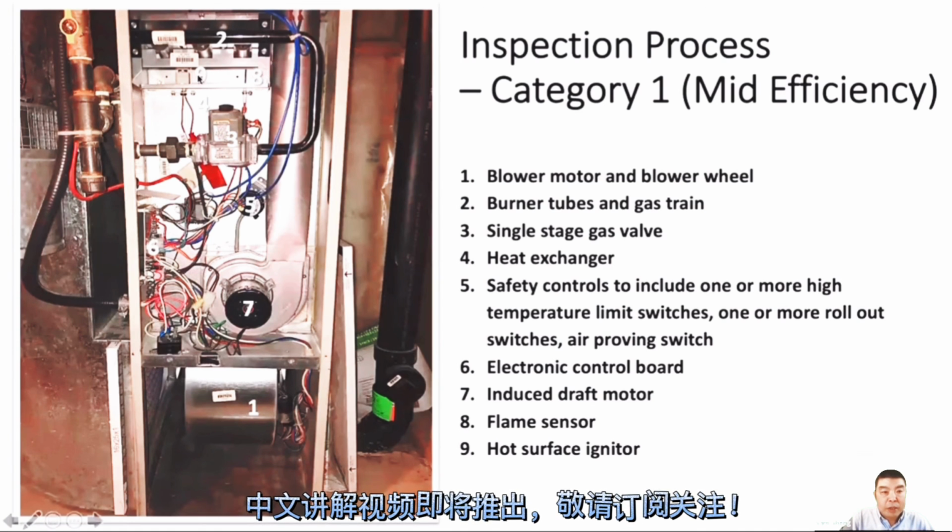Another thing you should know is that the material for the igniter is very brittle, so it's easy to break. When you check it, don't touch it. Just look around, and if you cannot see, maybe use a mirror. Don't touch it, because it's easy to break.